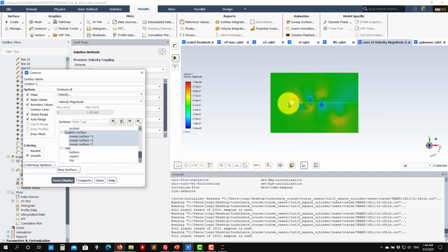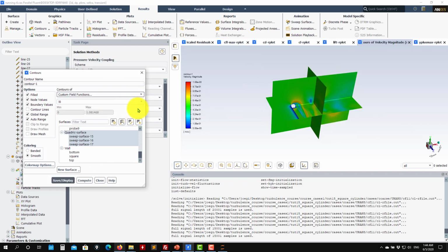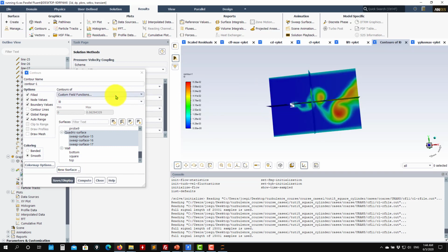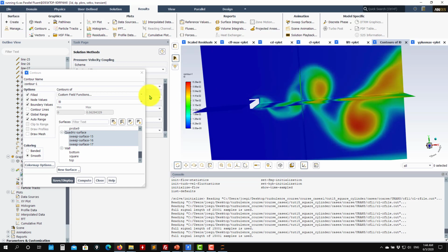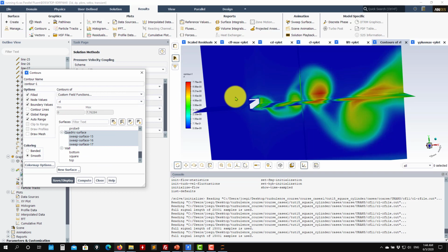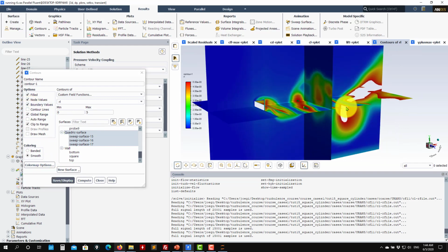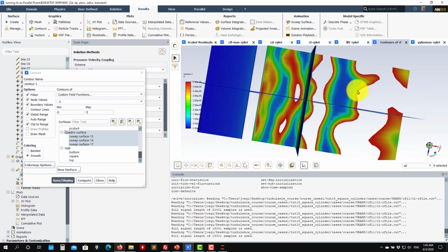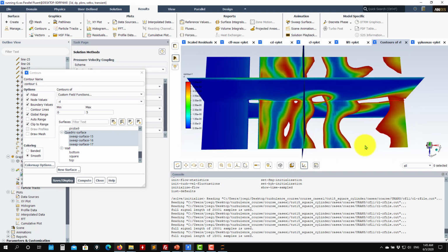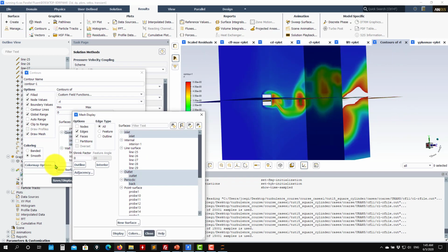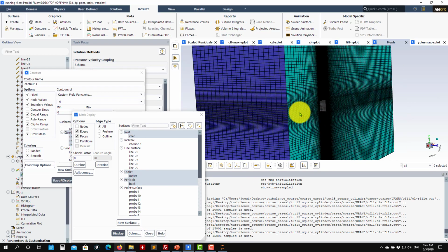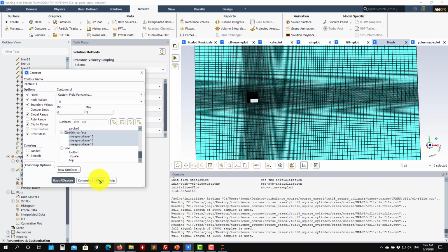Also let's post-process the data, because now we ran that one, and you will get the fields again. You get L0, and you see that it's very different from what we had. Now we have the actual vortex shedding. You can get RL, and you see that the values are much lower than 5. Just to remind you that we are working in the coarse mesh. So it's telling us that probably the largest vortex is resolved, but the others are not resolved well. Again, this is the coarse mesh. As you move and do the same with the fine mesh, you will get much better results.